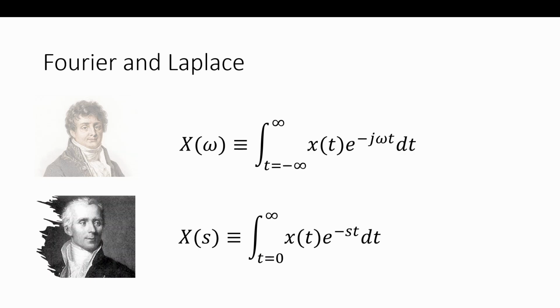First of all, what you're seeing here on the right with this complicated math, okay? You're seeing a product of two functions, and then we integrate the result. This multiply and integrate shows up again and again and again in DSP. It's a correlation or a mapping. I like to view it as a correlation. It makes a lot of sense out of it. So you may see it, and this is continuous time and discrete time. It's multiply and accumulate. Multiply and accumulate is a correlation, the same thing.